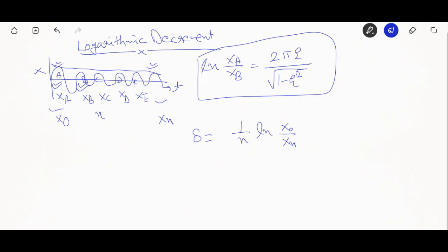One more thing, there is one more concept that will come in picture for the underdamped case, which is the concept of damped natural frequency, right? Why has it come into picture? Because we are using an underdamped system. So this represents omega d is equal to under root 1 minus xi square into omega n, right?